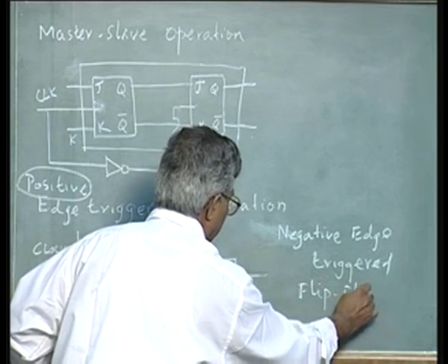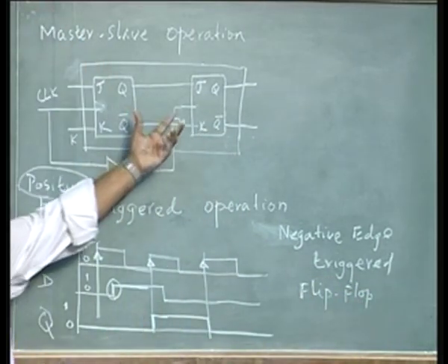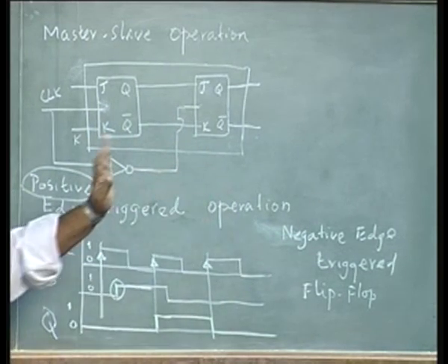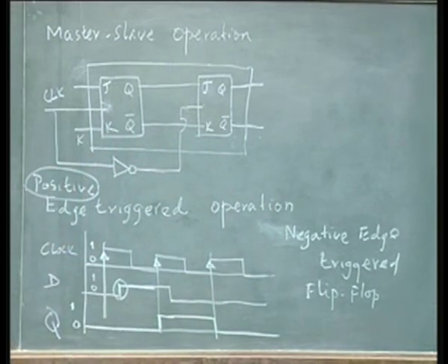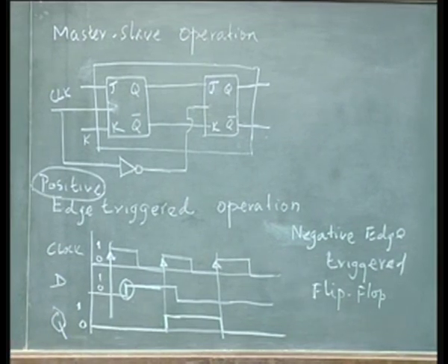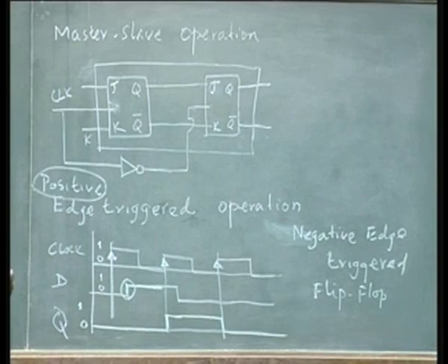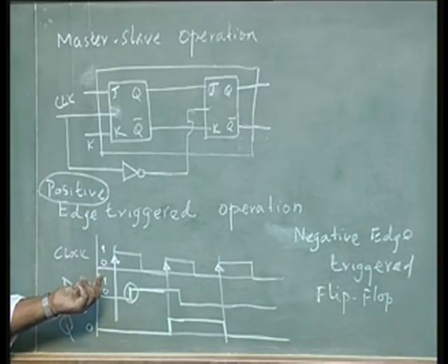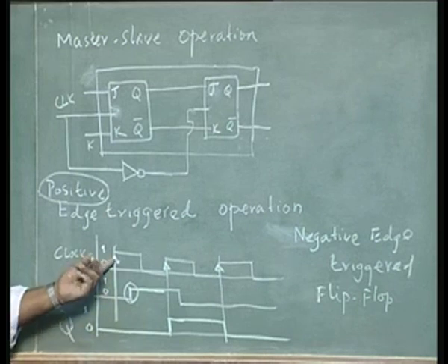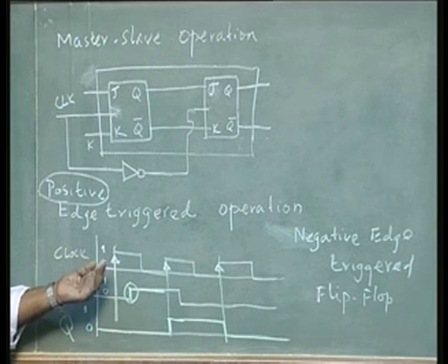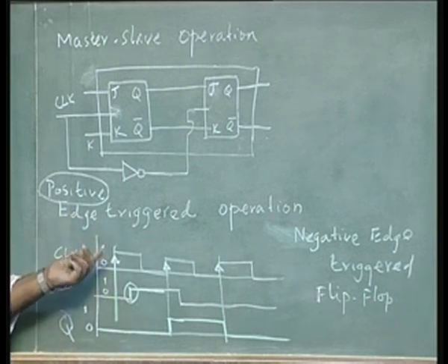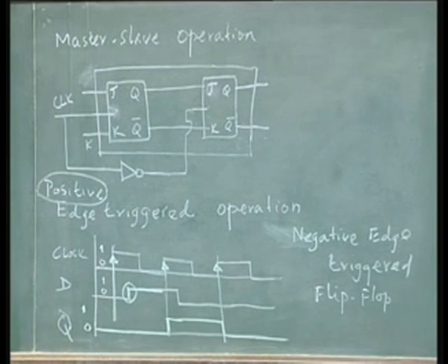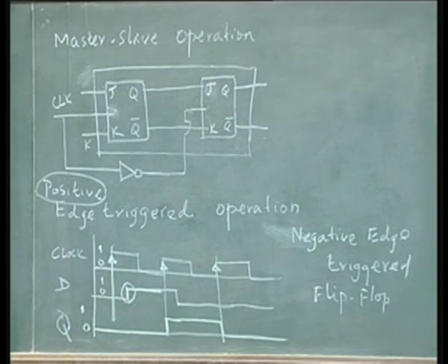So, these are the two options: the master slave option where you require an extra flip flop, because of that extra hardware and the little slowing down of the maximum frequency of operation. I will not worry about it too much. The maximum frequency of operation today is so high, and for most of the common circuits that we design in digital circuits, except in very, very high performance circuits, this is not a problem. On the other hand, we have an edge triggered operation where we will allow the output to change based on the input only once in a clock period. It can be at the positive edge of the clock or the negative edge of the clock. In one case it is called positive edge triggered flip flop, the other case is called negative edge triggered flip flop. And when doing so, we will still have to worry about the speed of operation decided by the propagation delay, but we do not have to worry about the toggling condition and all that racing condition.